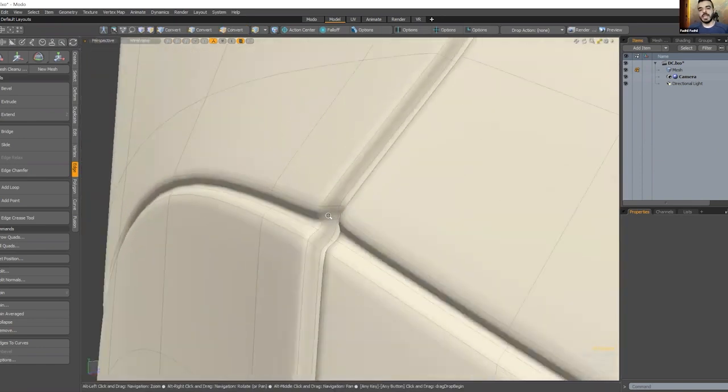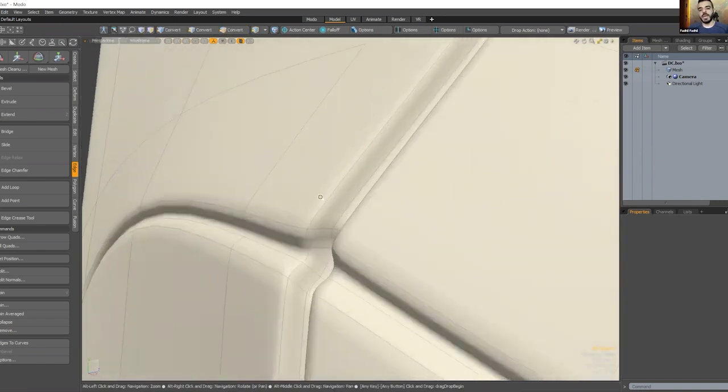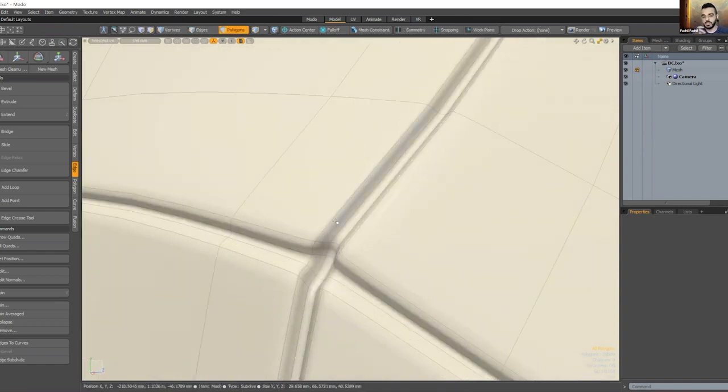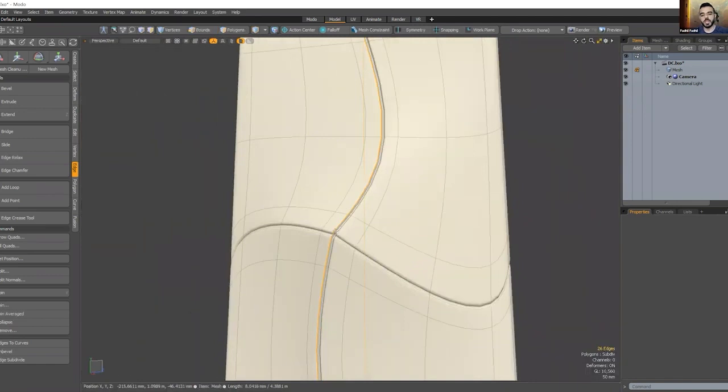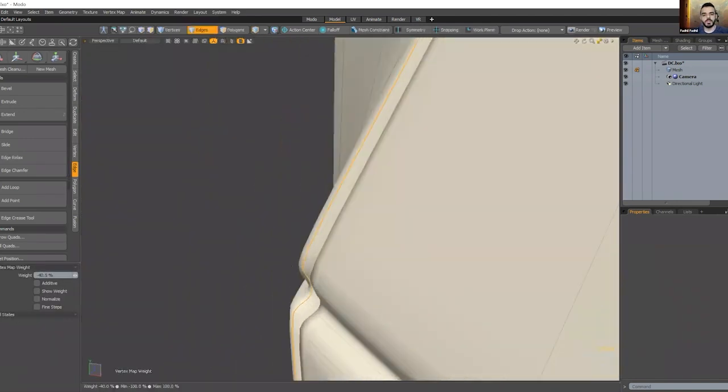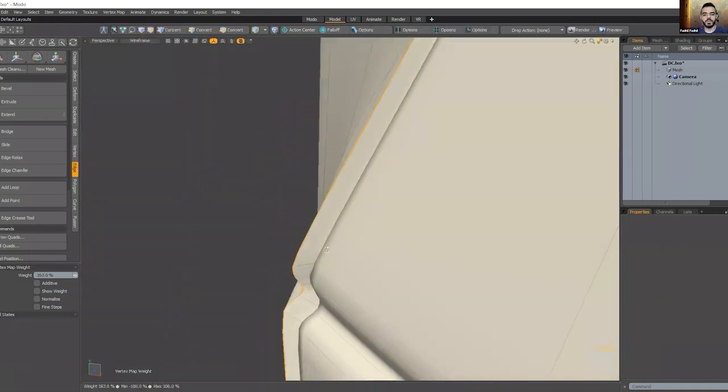So that's good. What I don't like about the design so far is that it has kind of blobby edges here, and I wanted to control the edges, so potentially I can give it some thickness. You can add thickness to the edges so that you sharpen the design a little bit and give it a little bit more definition. So if I wanted to sharpen this edge, I would double click on it and hit Shift W. And then the Shift W will give it a little bit more definition.